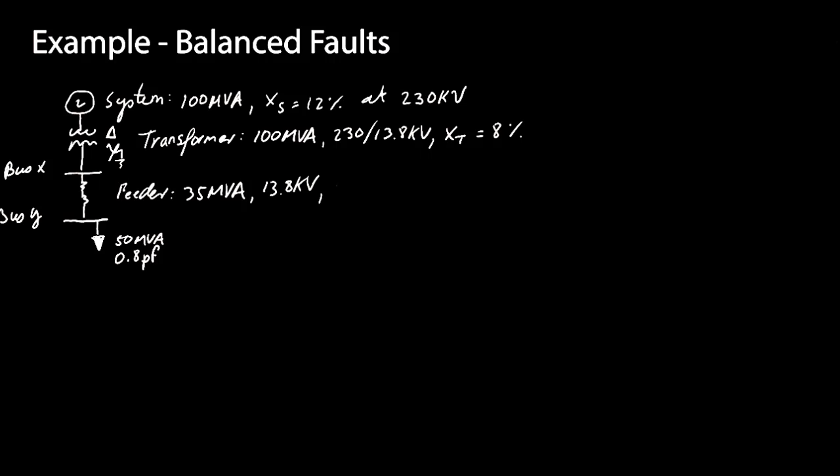And then it's going to have an impedance, which I'm going to call ZXY, since it connects buses X and Y. That impedance is going to be 0.1 at 85 degrees. And all of this of course is in per unit. So now what we need to do is take a couple steps to be able to calculate the fault current for a three-phase fault at bus Y. So we're going to have a fault again over here. So that's what we're trying to do for this example.